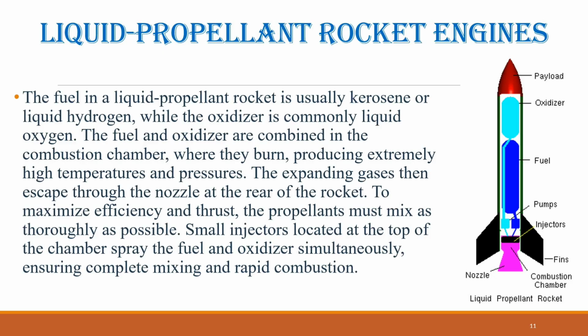Before entering the combustion chamber, the liquid hydrogen is circulated through small tubes that line the walls of the nozzle's exit cone. In cross-section, these walls resemble the edge of corrugated cardboard. The hydrogen absorbs the heat entering the walls, preventing them from melting. And at the same time, the hydrogen gains thermal energy, which makes it more energetic when injected into the chamber.